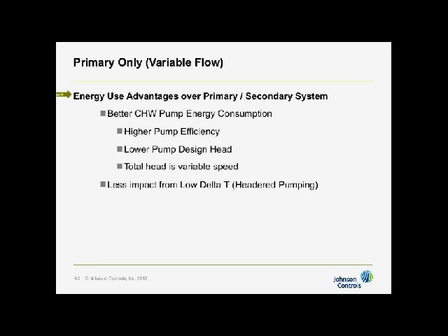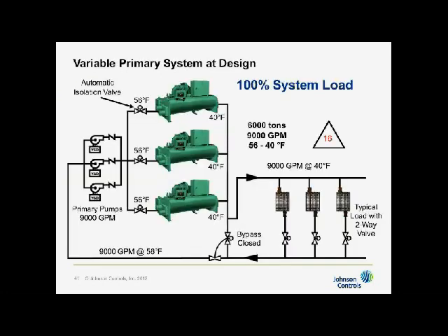Now we have an additional one. We have less impact from low delta T because we can, with headered pumping, mitigate low delta T. We can't solve it, you've got to do that at the loads, but we can mitigate it. Let's look at the same view we had of the primary secondary, but now VPF. Now we have our headered pumps over here.